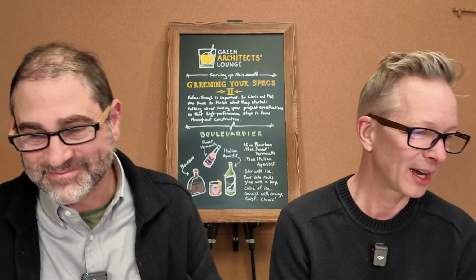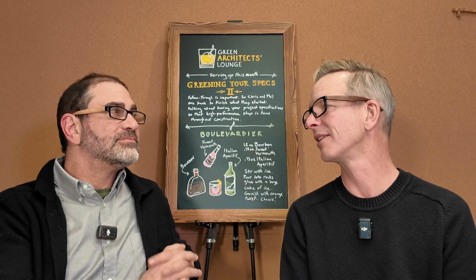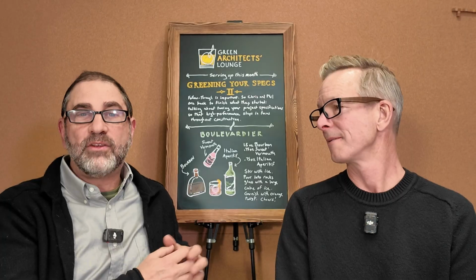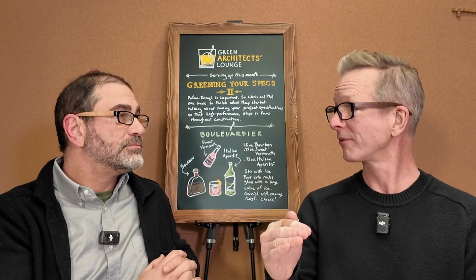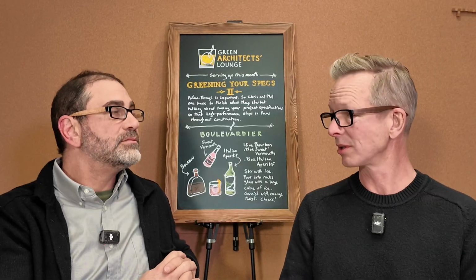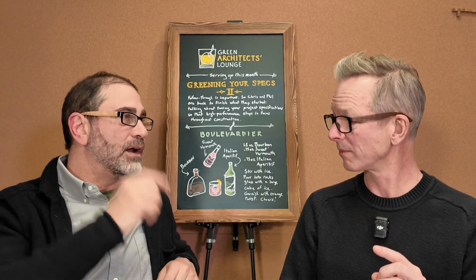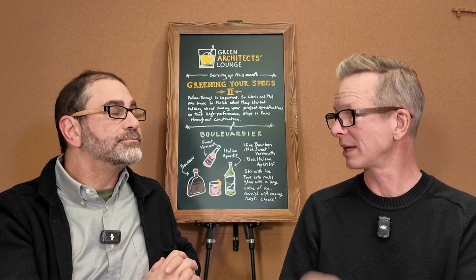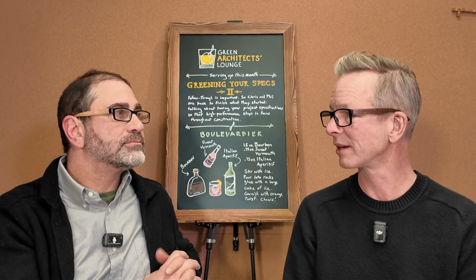There you go. And then, of course, you need to make sure you got your smoke detectors, all the life safety stuff that you need in your electrical specs. That's right. Prep for solar panels or put them on. Well, you just kind of glossed over the whole prep for solar panels. Because even if you're not doing solar panels, even if your client said, "Nah, I'm not doing that," you got to run a conduit to the roof. Do it now. Just do it. So easy to do now during construction, harder for retrofit usually.